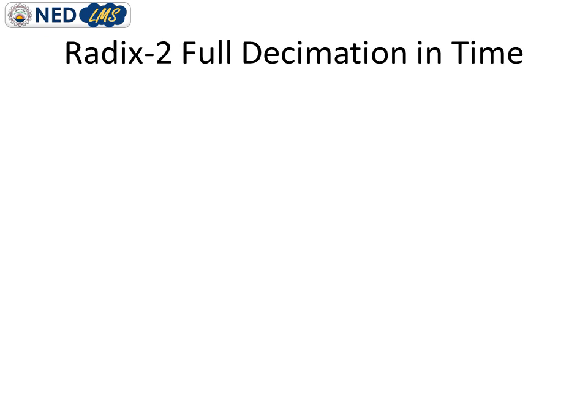As you know that 0 will not affect the output of your signal, so you can append 2 zeros to make the sample values equal to 32. So after doing this, you can actually represent 32 as 2 raised to power 5. And as you have appended zeros, last two zeros or starting two zeros, this will not affect your actual output. So this is the better technique.